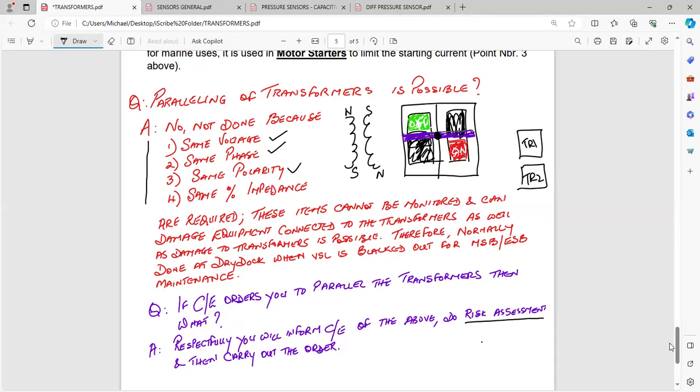If they are going to do painting, remove the old paint by scraping. Otherwise, layer upon layer of paint is going to come on that, and that is also going to add to the heat. The dissipation of heat won't be good. Apart from that, check any of the connections. Obviously, you cannot check a live transformer. You'll have to do it for one that is not in use. Other than that, there is no other maintenance that you have to do.